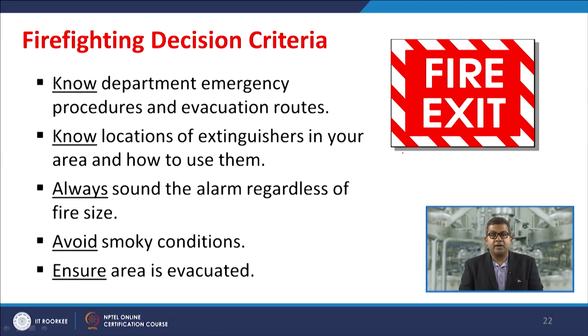Now, if you are heading to that particular department, you must ensure that the area is evacuated. Usually you may follow the head count process. You must know how many persons are working in that particular process area, and ask them to leave and assemble at an open and safe space. So, you do a head count, and by this way you ensure that the area is evacuated and nobody is entrapped within the plant.